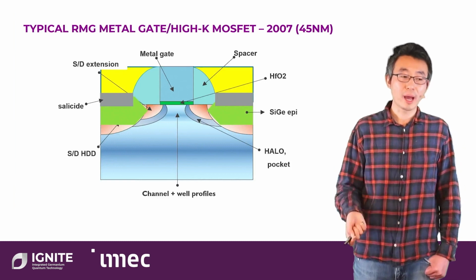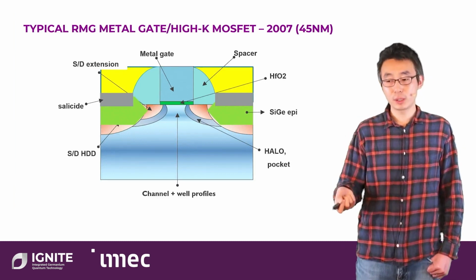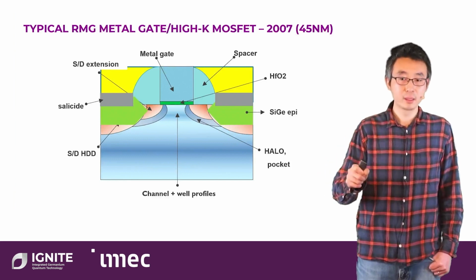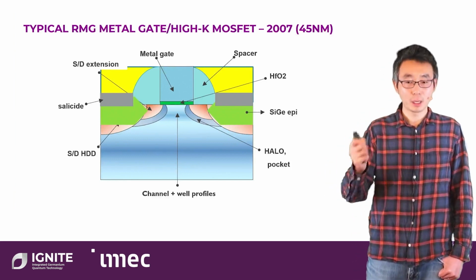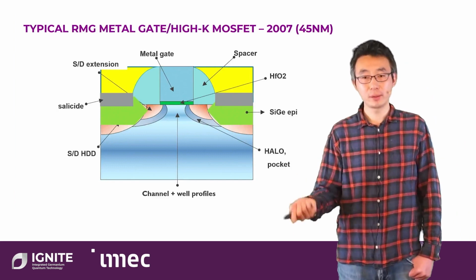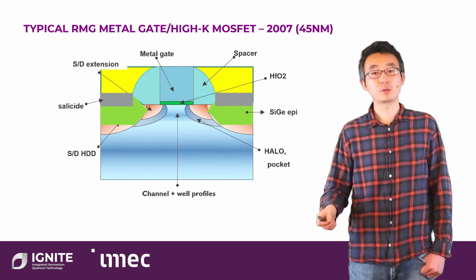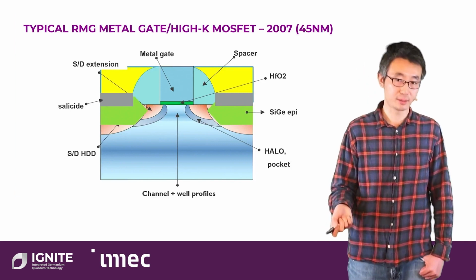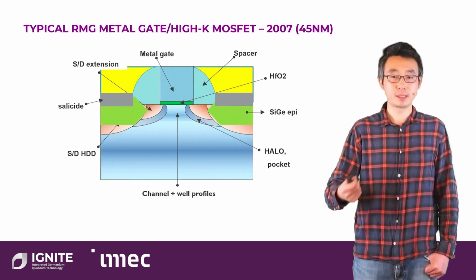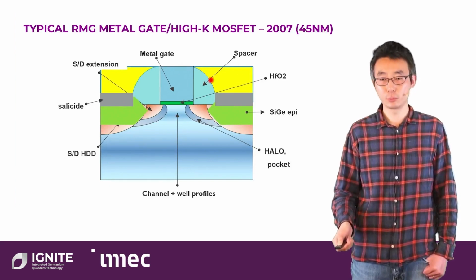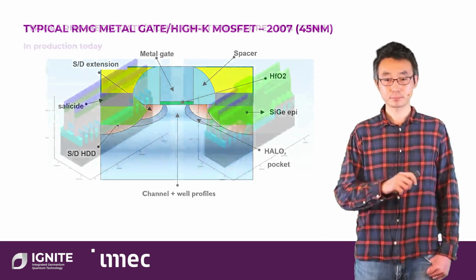So people introduced high-K material, with which you can achieve a very narrow effective oxide thickness with a much bigger physical thickness. However, since high-K reacts with the polysilicon, you have to use a metal gate. But the metal gate is not compatible with high temperature processing, so you need to implement the replacement gate. That's why you have the high-K metal gate and the replacement structure around it.